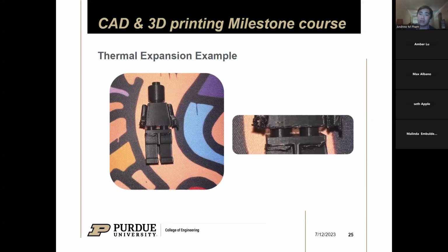Yes, we'll get into that. So generally, I like to use 0.2 millimeters as a general idea for tolerancing. It works pretty well for me. Obviously, like you asked, your printer does affect the amount of tolerance that you might need to add. But in general, 0.2 millimeters is a pretty good safe bet, right? I work a lot with metric hardware whenever I make parts. I make a lot of things that use M3 bolts.